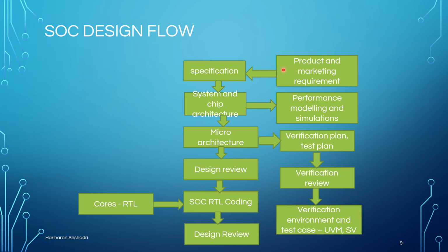So you take that, and the architecture team prepares a specification document. Based on that specification document, we do system architecture. What is going to software, what is going to hardware. So we prepare that, right? That's a system specification. From the specification, we write a system level specification. From there, we write what components are going to software, what components are going to hardware, and then prepare the chip system architecture. Then based on that, do the software architecture separately and hardware architecture separately.